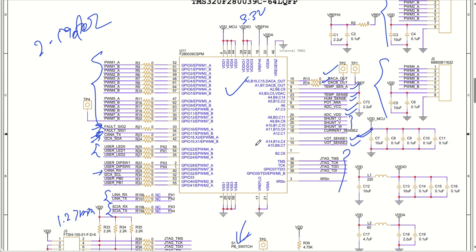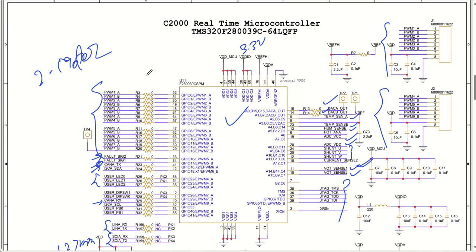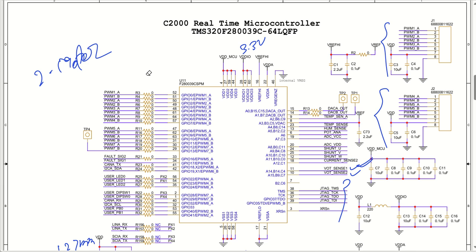We have taken into account this microcontroller. If you do have any questions or need any understanding about microcontroller system design, how to do pin mapping for different peripherals, and what application is needed: I have utilized almost all the pins in this particular microcontroller, but your job would be to use as few pins as possible, because most of the pins can be left unused.